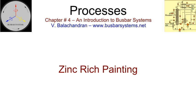Zinc-rich paint is classified based on the type of binder used during its formulation. The binder can be either organic or inorganic. Epoxy, polyester, and polyurethane resins are organic binders, while silicates are inorganic binders. Zinc-rich primers with inorganic binders are more effective in providing cathodic protection than those with organic binders.